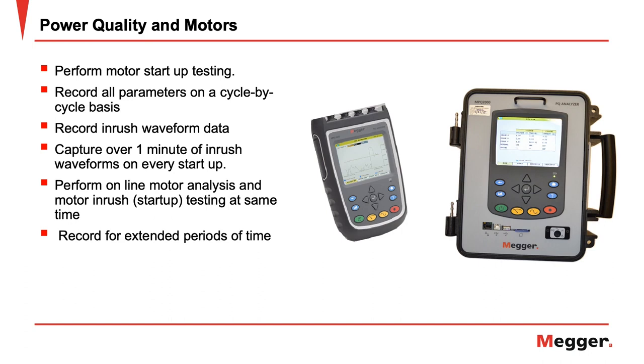During startup, the inrush current can be as high as 13 times the full load rating of the machine. Additionally, the rotor bars are under their highest torque loading, and that can be up to 3 times full load torque during the startup. As a result of this high current draw, voltages can sag. Keep in mind, excessive sags result in longer startup times and additional winding heating and rotor bar stress. Quantifying the voltage sag can identify power supply stiffness issues that, when corrected, can improve system efficiency and prolong motor life.